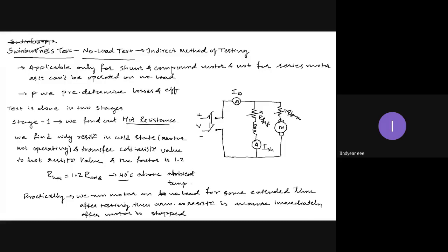In AC machines, last time you calculated 1.5 times the armature value. You remember? RA in alternators or synchronous generators, you took some per phase value of resistance, 3.5 ohms, and multiplied it by 1.5 again. That is for skin effect. In AC machines, we observe skin effect. There is no skin effect in DC machines because the reactance in DC is 0. Therefore, we don't multiply by a skin effect factor here. Whatever value we get using the multimeter, we take it.